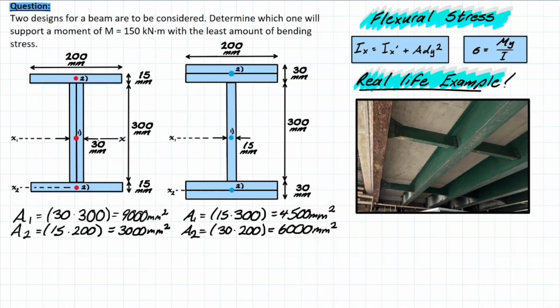But the reason that I place it at the center here, that x global coordinate is right at the center, is because we are going to have a zero distance away between the local and global axis of this central shape here in the center. So D1 is going to be 0. That's going to be the case for both of these members here.